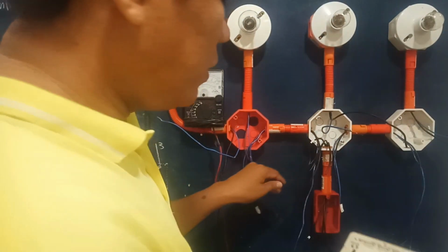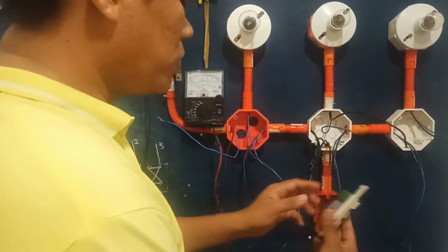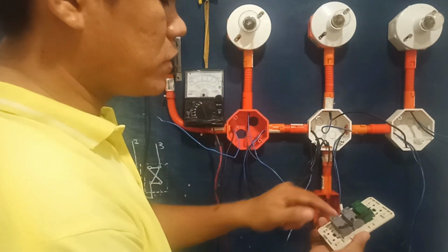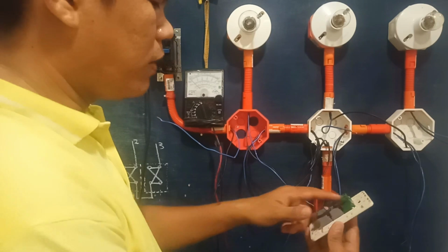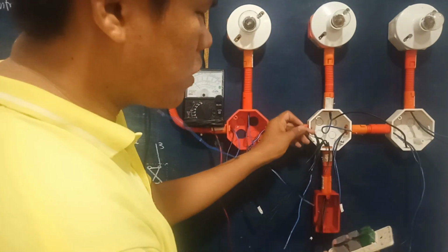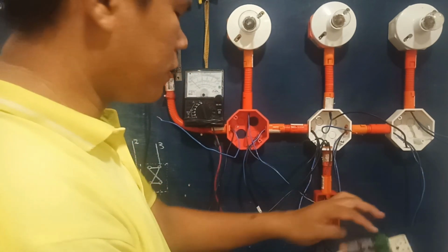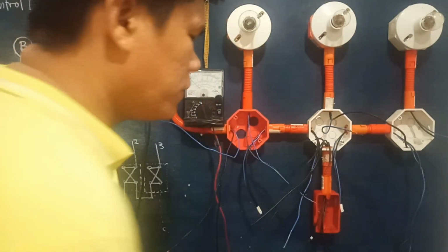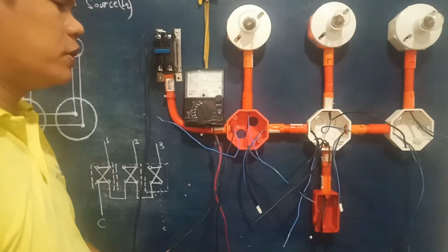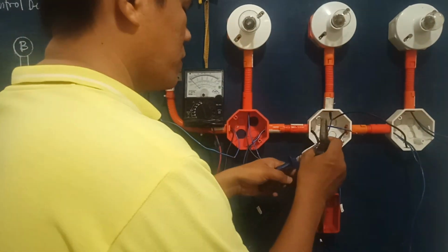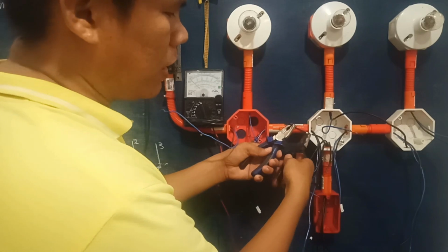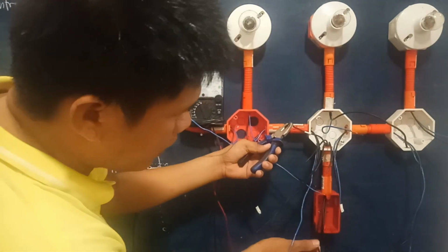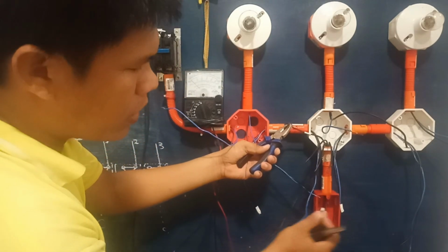Next we have here the 3-gang single pole switch this way. So we do the jumper already in this case. So we have the jumper wire, and then all we have to do is to connect the common wire, terminal 1, 2, and 3. So let's do this, guys. So we will do first the common terminal. Okay, so common terminal. So we have here an indicator for the common terminal, this one, white electrical tape, and also here for the common terminal connection.